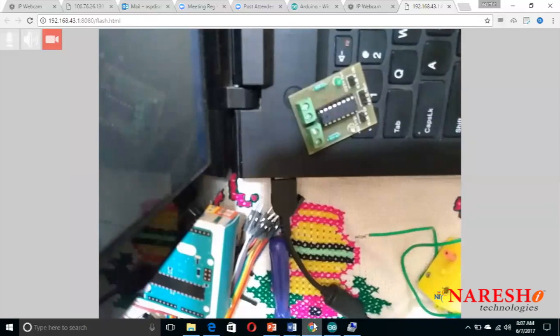The voltage coming from the Arduino board is very low for running our motor. If we directly attach our motor to the Arduino board it will not run, so we use a motor driver board. It takes whatever voltage comes from the Arduino and increases it or makes it suitable to run the DC motor.